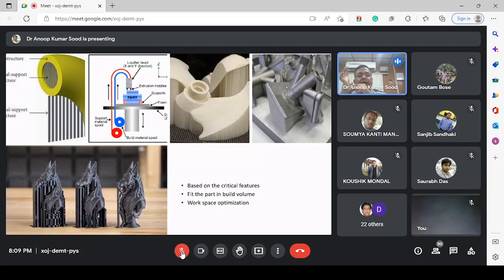Despite so much application and use of the powder bed fusion process, this process is not able to build a part which is less than 500 micron size there, whereas stereolithography is able to do that. So that's why I have chosen two distinct processes, to understand the problems there, to expose the problems of the process. So later on, faculty members and researchers can adopt this to modify that. But it is not that you only go for the development of a new machine. Even the pre-processing stage, which we have discussed till this point, needs improvement. You have to think after this introduction how we can improve it to be feasible for microfabrication.